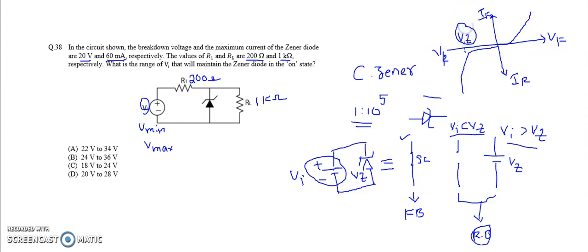Why are we calling this the breakdown voltage? Because if we keep on increasing the reverse biasing voltage of a Zener diode, at one particular voltage, called the breakdown voltage, almost most of the covalent bonds in the Zener diode start breaking down. Whenever the covalent bonds break down, there is a huge release of free electrons that leads to a sudden increase in current across the Zener diode.